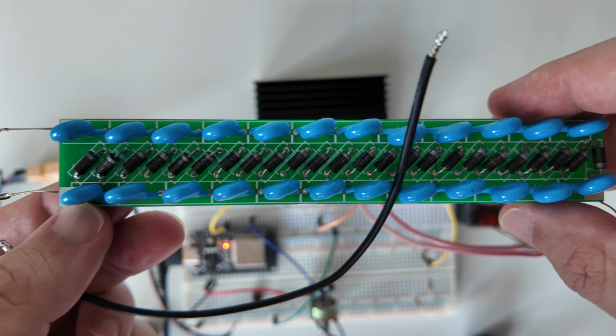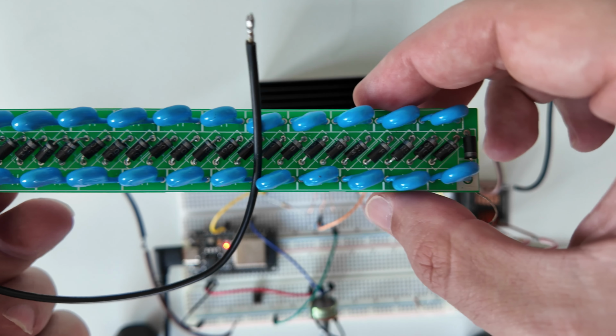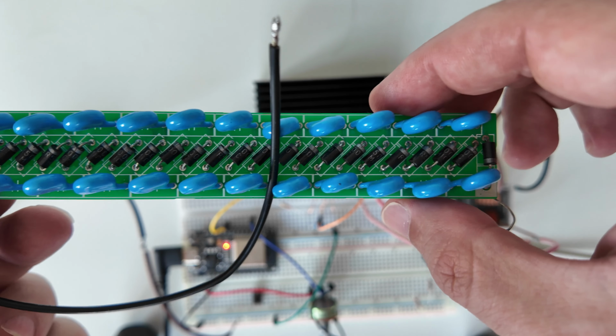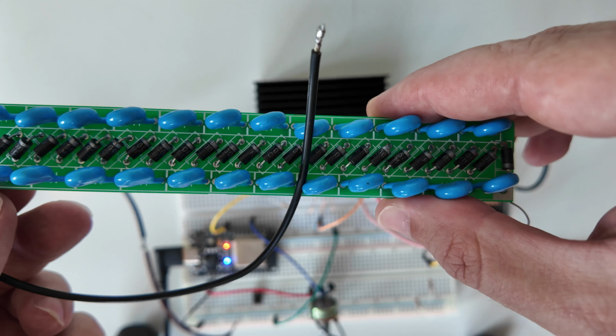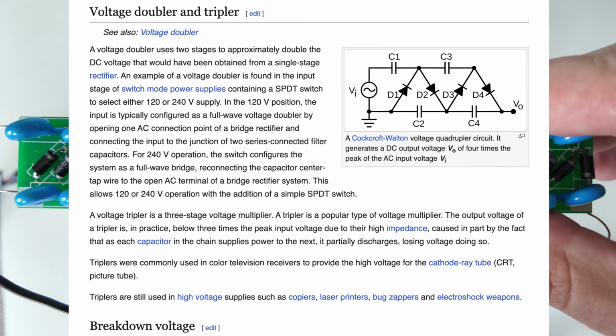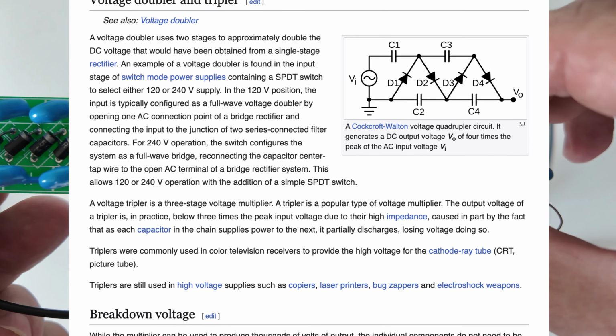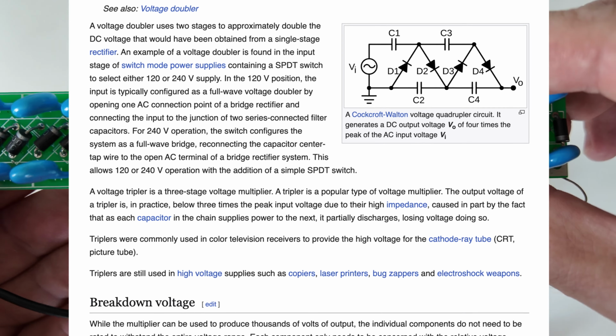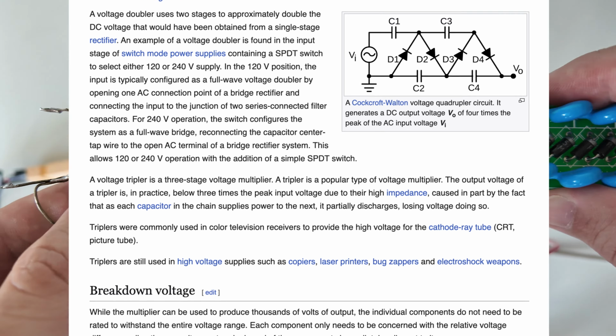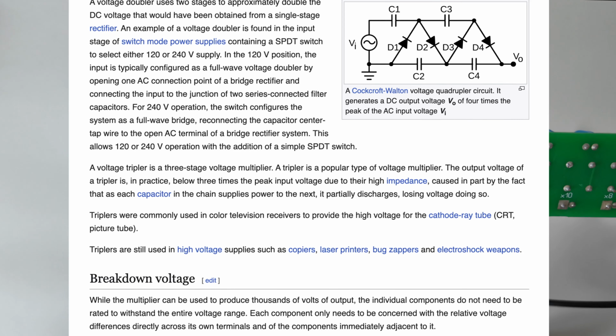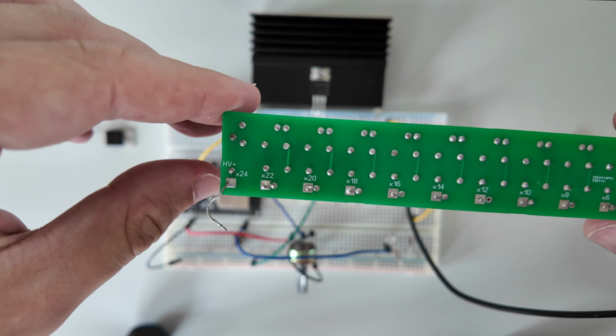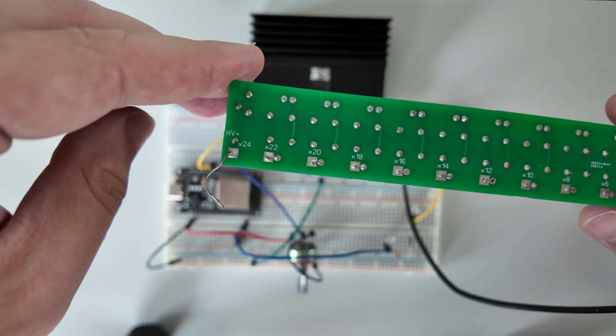As we can see, the voltage multiplier contains a big set of diodes and capacitors. Intuitively, the logic is simple. The AC current is changing its direction many times per second, and in the first half period the capacitor is charging, but the diode is preventing this current from going back. Of course, the process is not ideal, but still we have a much higher voltage.